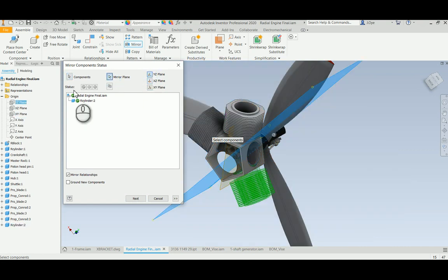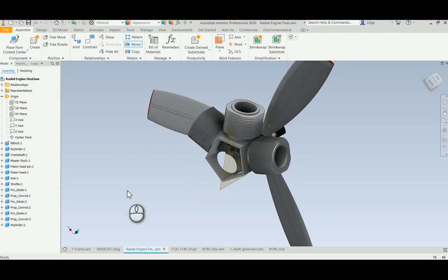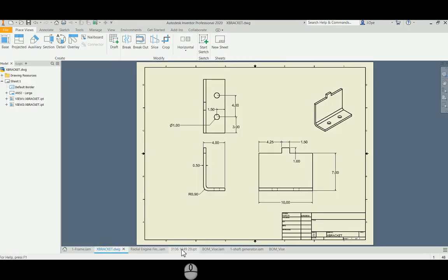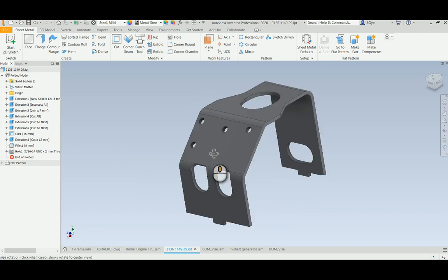All right, so toggling over to this sheet metal part, the next few updates are related to the hole command. So I'm going to go into my part model tree of this sheet metal part and just double click on that hole, go in and edit it here. So one thing that was added to the release of 2020.1 is this toggle button here, allow center point creation.